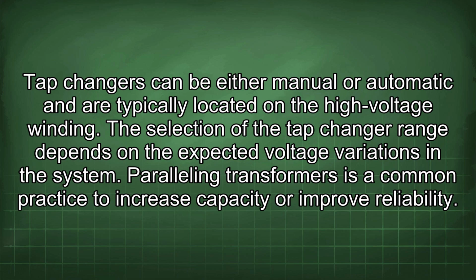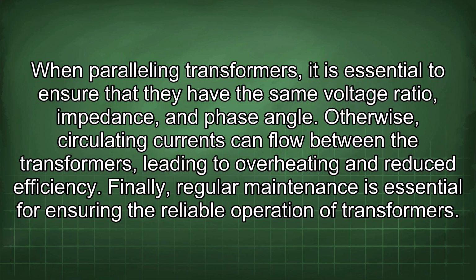Paralleling transformers is a common practice to increase capacity or improve reliability. When paralleling transformers, it is essential to ensure that they have the same voltage ratio, impedance, and phase angle. Otherwise, circulating currents can flow between the transformers, leading to overheating and reduced efficiency.